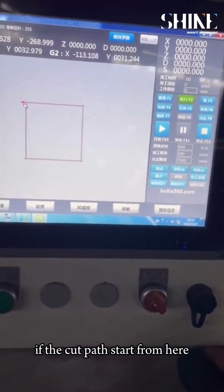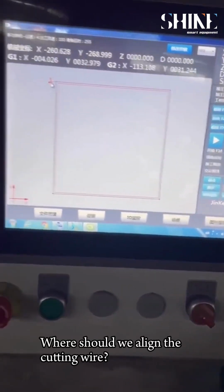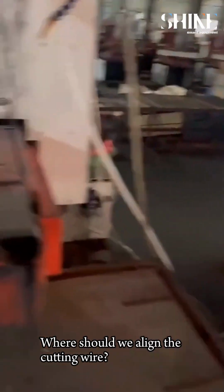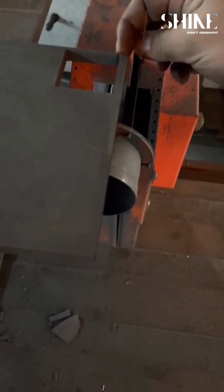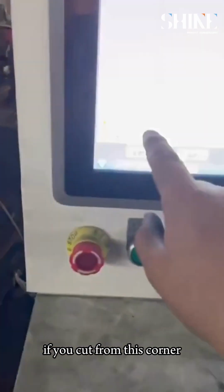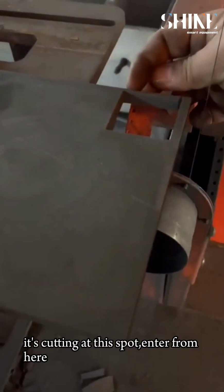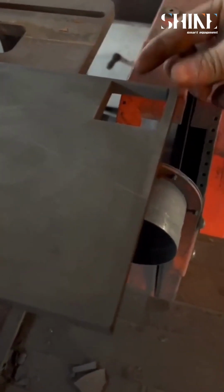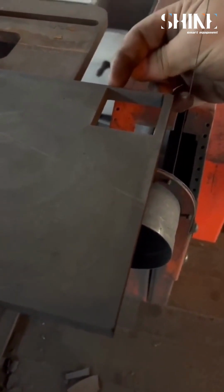If the cut path starts from here, where should we align the cutting wire? The cutting wire should align with this position. If you cut from this corner, cut from this lower corner. It's cutting at this spot, enter from here. Calculate the distance, come over from here is 50 millimeters.